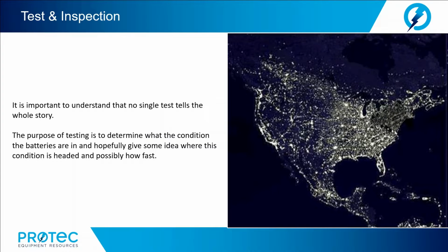You do not want to find out during a power outage that the batteries did not have sufficient capacity and your load was dropped sooner than designed, or that the entire system failed due to a single component failure, and that all of this could have been predicted and prevented. Because of this, it is always best to have as much test data as possible and be sure to record the data.